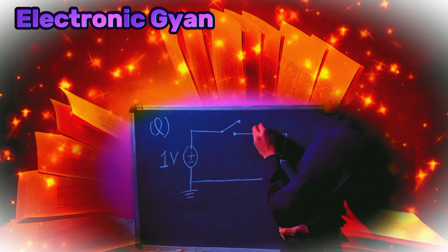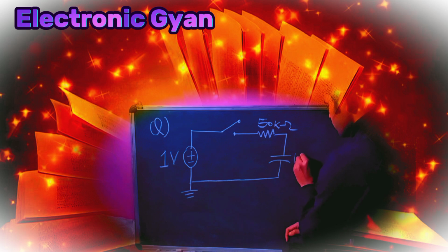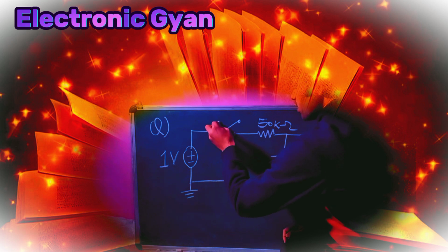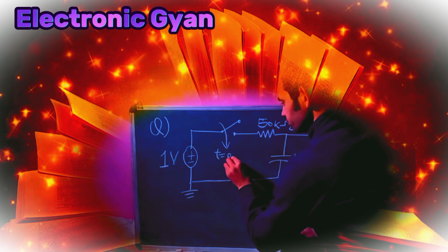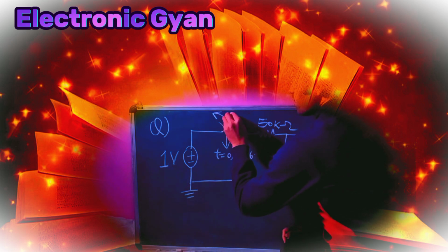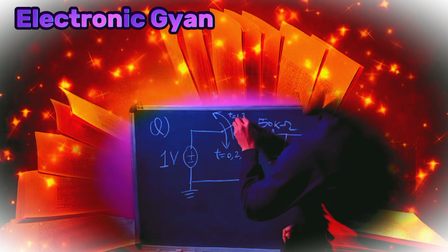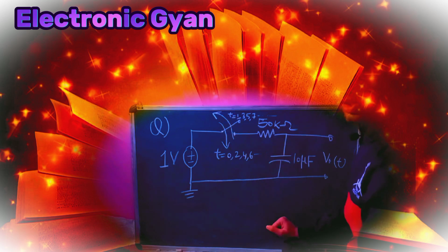Now this is, let's say, 50 kilo ohm and this is 10 microfarad of capacitance, and I want to find the output voltage V0 of t. When this switch is on at time t equal to 0, then at 2, 4, 6 and so on, and my switch is off for time t equal to 1, 3, 5, 7 and so on. So this is what periodic switching is.